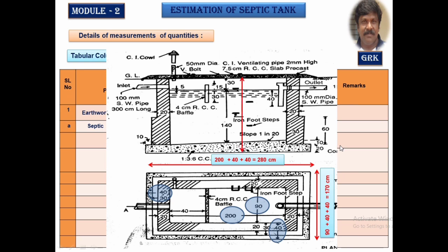Let us calculate the depth of the section. As I said, it is taken below the earth level. It is 30 plus 140. 140 is to the center of this sloping concrete. So, we have to divide this into two parts, to get the average thickness here. It is 0 at one end, 10 centimeter at the other end, and the remaining depth is 20 centimeter.